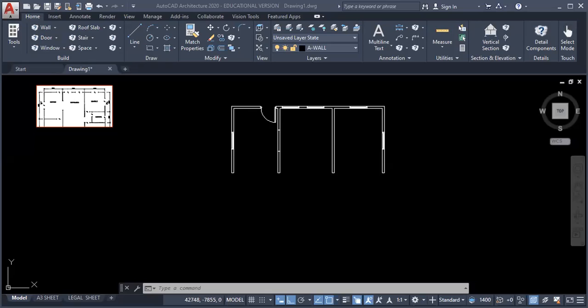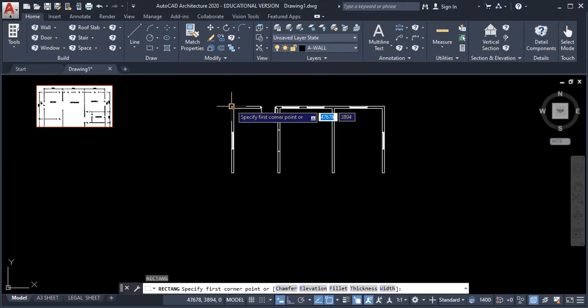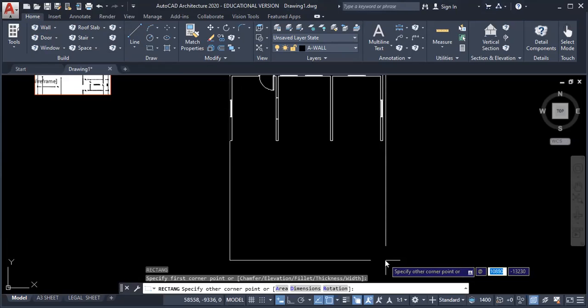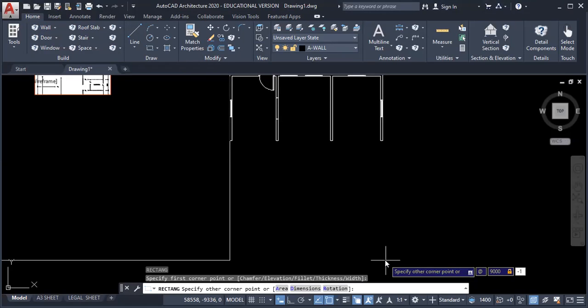So what I will do, I will draw the outline for the roof, outline for the wall, then offset that by 450. Okay, so my next step is to draw a rectangle. So I type REC, enter, and I'm gonna start here. I'm gonna use @ shift @. So the horizontal axis is 9000, comma, minus 10,000, enter.